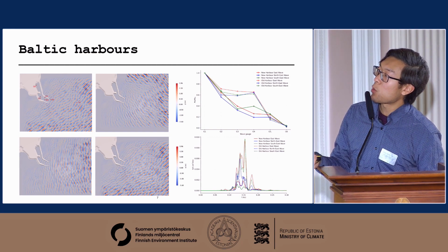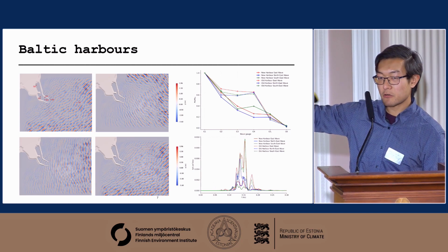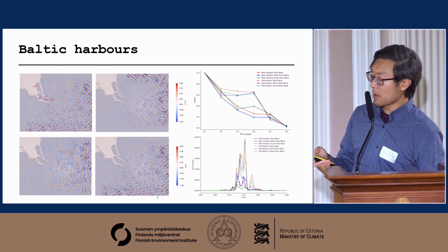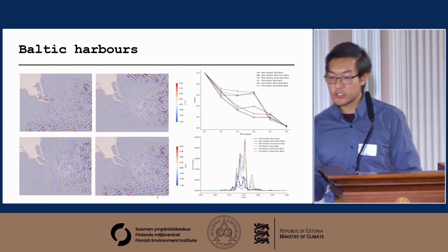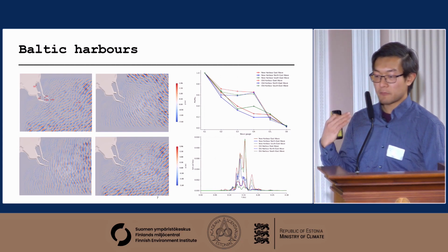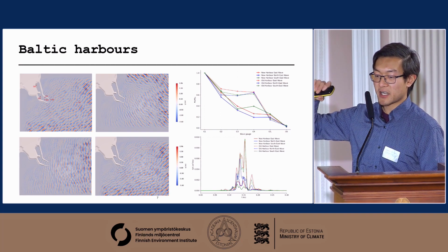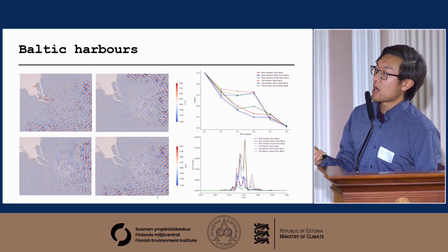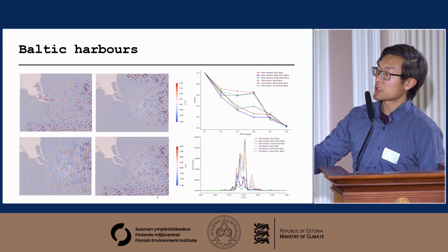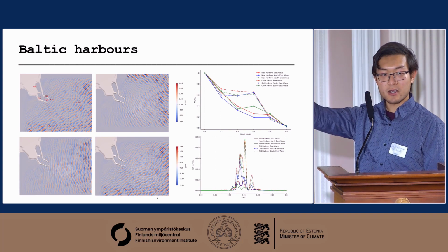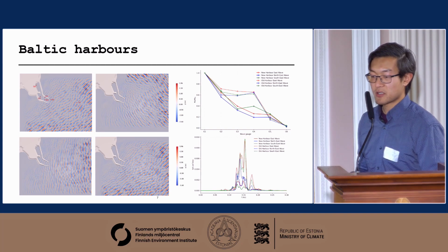And you can see wave height has been reduced significantly, especially along the navigation channel for the ferry. But also you can see, if you look at the green line, there's a peak at wave gauge 4 that has increased wave height for the wave direction from the southeast, which means that it's the wave direction here. So the wave is coming straight into the harbor, aligned with the navigation channel. So that creates the most dangerous scenario.